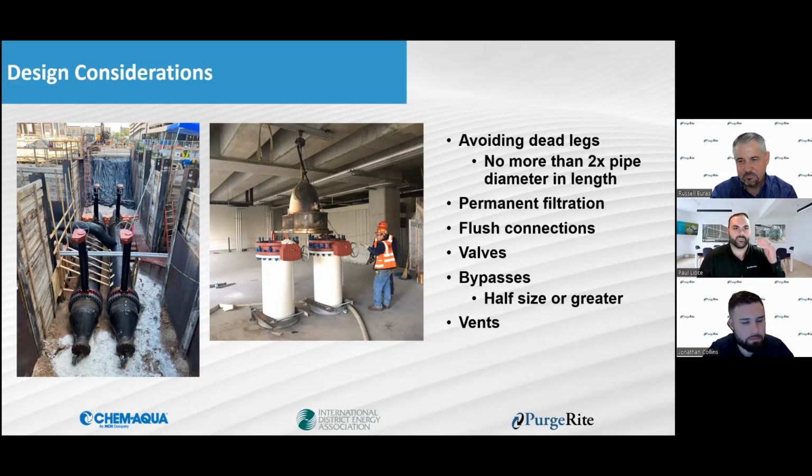This was our quality during our flush. This was our passivation period. So you have those final owner documents. There might be a comment in there that says you had a 4-foot pipe dead leg for 18 feet, and that could result in that. By giving yourself that time and bringing the people in, it allows you to find these issues and minimize liability down the line. Because those bypasses are very easy to put in, and they're a game changer.